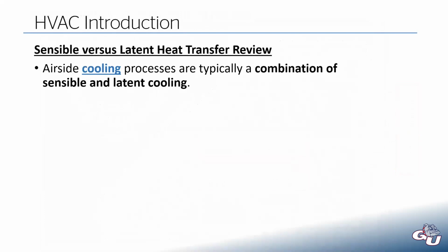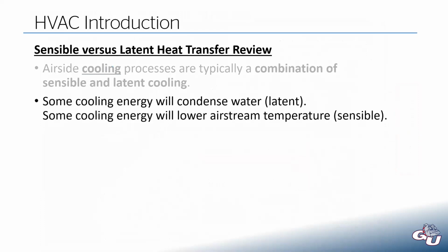So heating processes are easy. Cooling gets a little more complicated because cooling processes are typically a combination of sensible and latent cooling. When we cool down that airstream, some of that cooling energy will condense the water, and some of it will lower the airstream temperature.